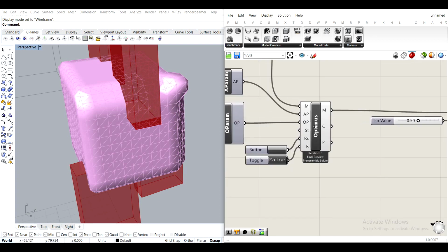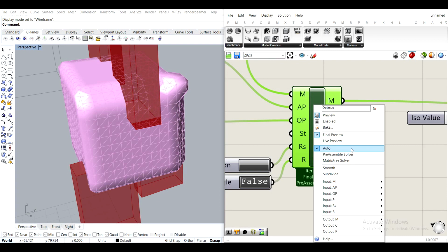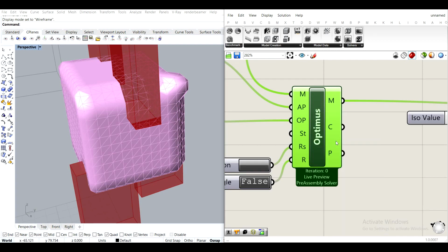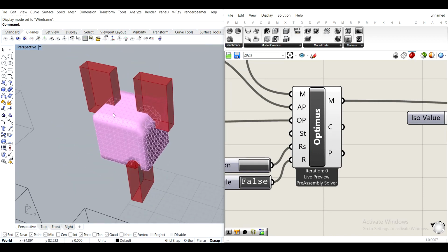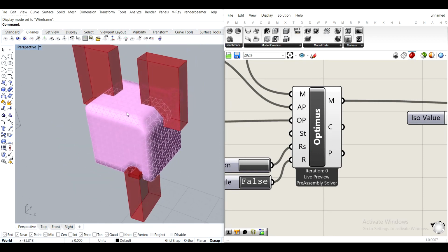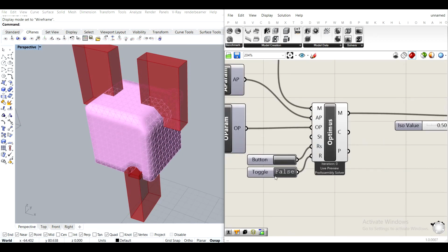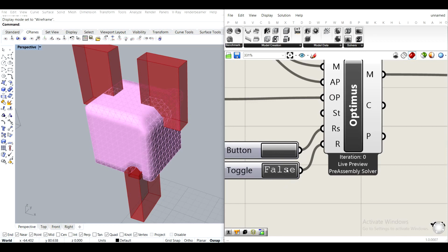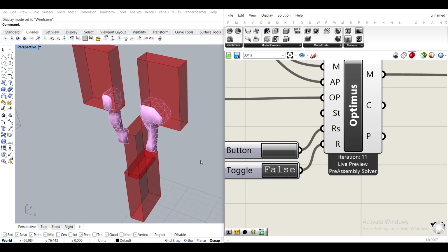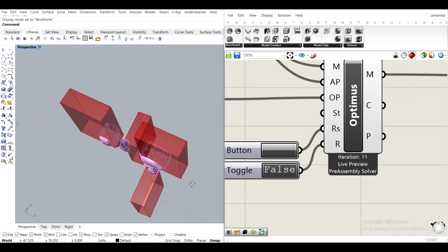And one last thing before we run the simulation, I will right click on the solver itself, and instead of using final preview, I'll choose live preview. Because what this is going to do is show me every step, so it's going to be easier to understand what is going on. Right. So now I'll hit reset, I'll hit true, and I can see it tried to do...